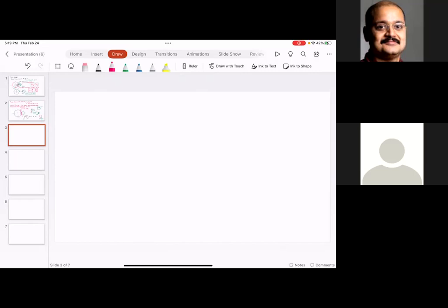So what are the fundamental types of gears? It depends on how the axes of the input shaft and the output shaft are oriented. Let's look at if these two shafts are parallel. For example, if the input shaft is parallel to the output shaft, then if you look from the top, the gear train is going to look like this.